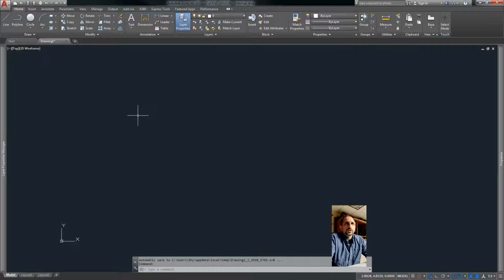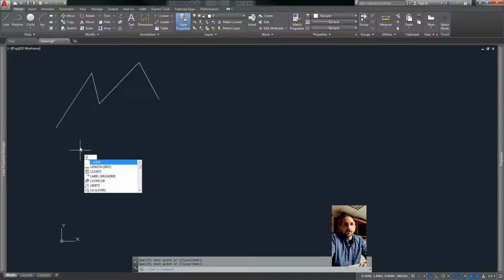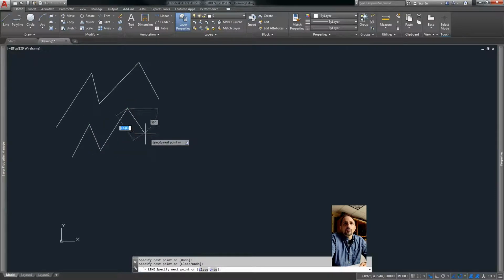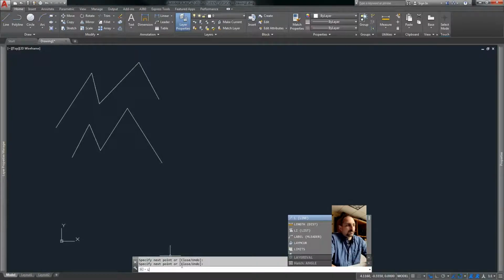However, once you learn the various commands in AutoCAD, for instance, drawing a line, I select the line command and then I enter my command. You can also enter the line command through the keyboard, which is actually a quicker option. If I just hit L on my keyboard and I right click, it automatically selects the command for me. It's a little bit quicker. I use the keys to enter my commands and I can go. Third option, if you're curious, I can also insert commands through the command bar at the bottom.